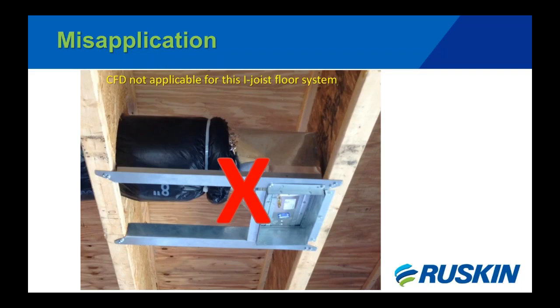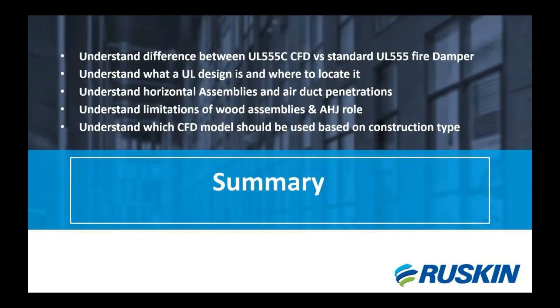So this is wrong because of the floor system type and also because the damper is just not suitable to maintain adequate protection. So this example would be one where it's definitely a judgment call by the authorities having jurisdiction. We have little support for this because it's just not been evaluated and our dampers aren't even qualified to perform in this type of application. In this particular case, I'm not sure how they solved it, but this was just the initial information we were presented with.